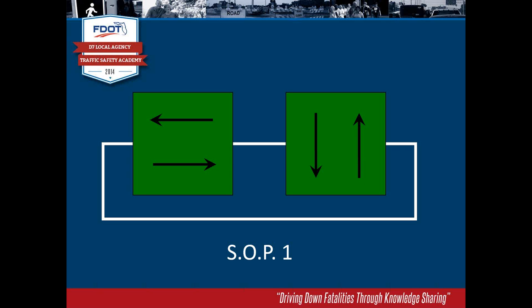This is the real simple signal operation in DOT. The DOT label on this is SOP1, or Signal Operating Plan Number 1. It's a two-phase signal. The first phase is east-west, and the second phase is for north-south traffic, and then you come back around and start east-west again. So this is real simple. It would be called a two-phase operation, or SOP1, and you do see it at a lot of intersections around, again, fairly minor intersections, but it's a real simple two-phase operation.